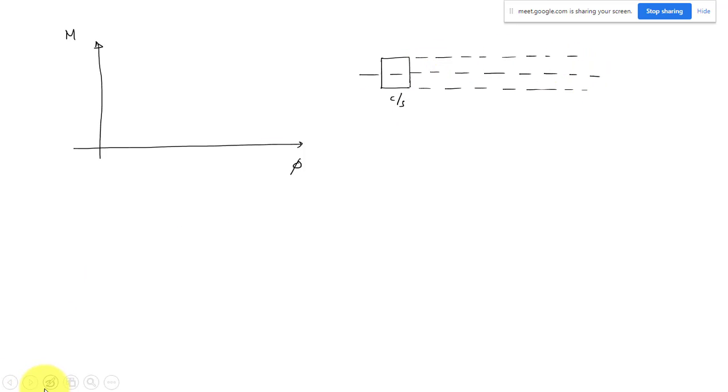Initially it will be elastic. So this is the critical stage, where your extreme fiber stress is sigma y. So the graph will be like this, initially straight, then we have a small curve, then it is constant.